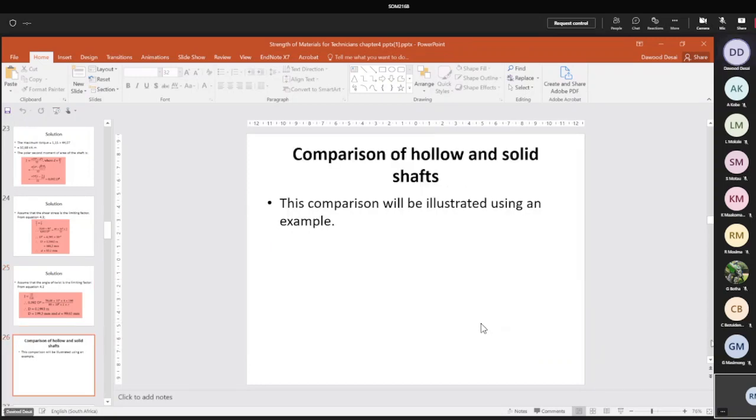Right, people, like we had yesterday, you get shafts in series and shafts in parallel. You get the exact same thing now with torsion. Same theory, nothing changes. The only difference, instead of forces, you talk with torques. So you can get torques that are applied intermittently along the axis of a shaft, and you can get torques that are applied at the outside ends, like I showed you now. The theory is nothing changed, only the force changes to torque. The hand thing that I taught you yesterday, summation of torques to one side of the section.